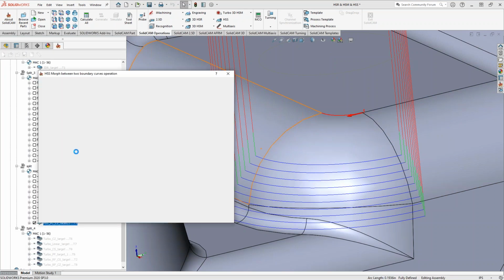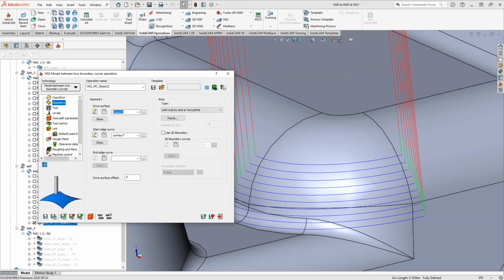It is one of the ways you can do toolpath trimming, and pretty much it is one of the more basic ways as well. There is a lot of modification you can do to surfaces and that sort of thing, but some of those might not be available in the 2.5D or Express packages of SolidCAM. But definitely the limit by 2 points is part of that basic menu.